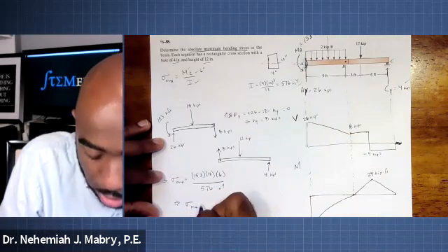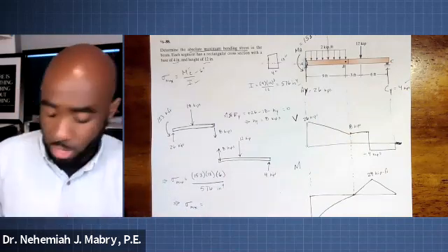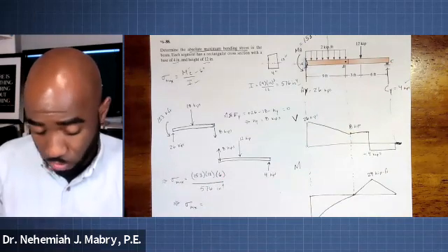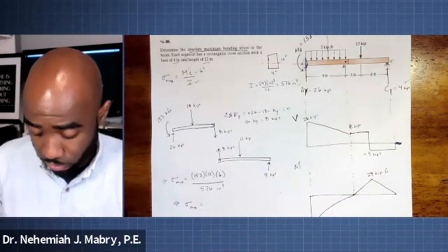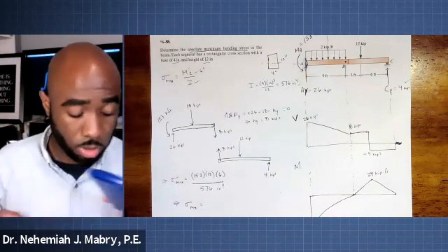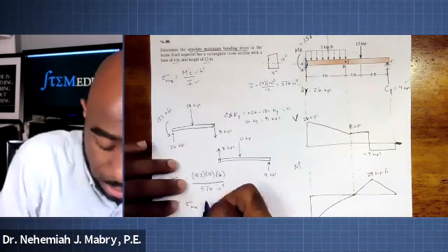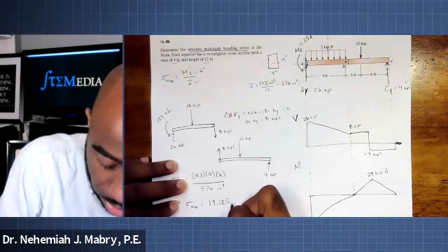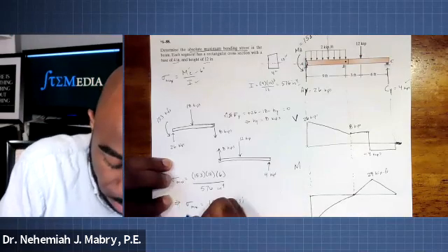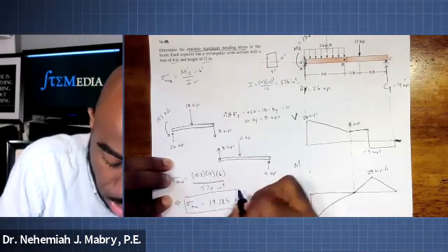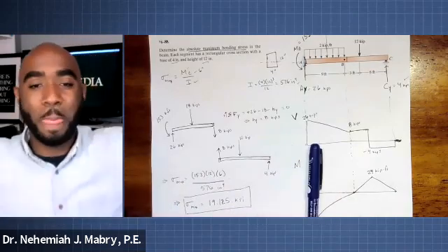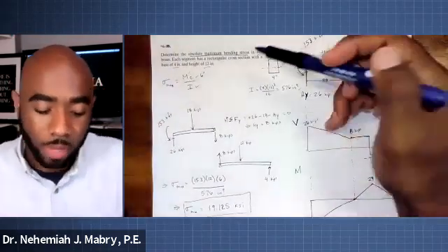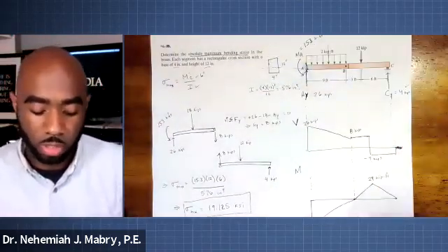So if you grab your calculator, as I grab mine, we can find the answer together. 153 times 12 times 6 divided by 576 equals 19.125 KSI. Do you concur, my friends? I hope so, because that, for problem 6-88, is the absolute maximum bending stress.